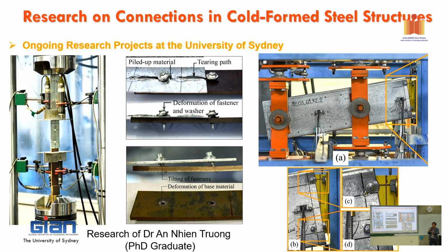Right. So remember, when you design a connection, for example, for shear or screw connection, what you do now is you just check shear or bearing or whatever in one screw. And you multiply by the number of screws that you design. That's it. That's the capacity.